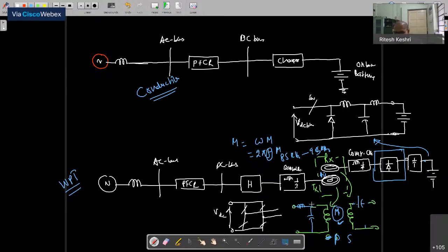But in any case, what we do is first size the system, then calculate what should be the inductance and mutual inductance. After that we start designing the coil. That is done. Then we try to think of using compensation circuitry to see if it is possible to improve that mutual inductance or not. Different compensation strategies will give you different types of improvement, and it is you who has to decide which is most suited for you.